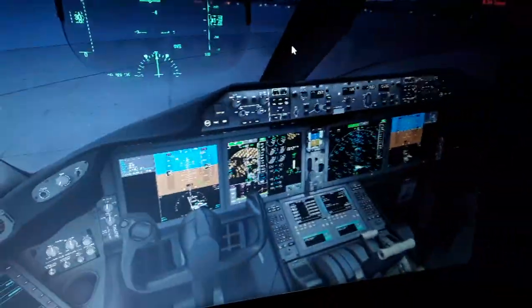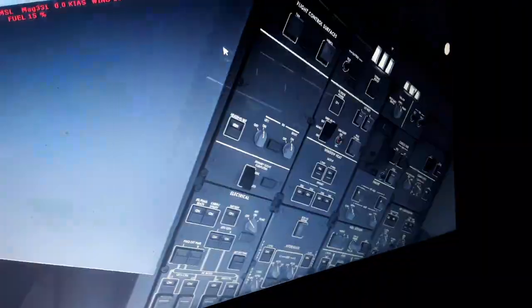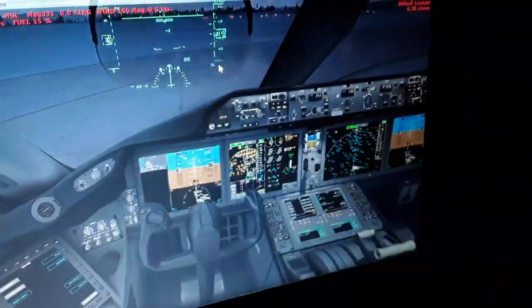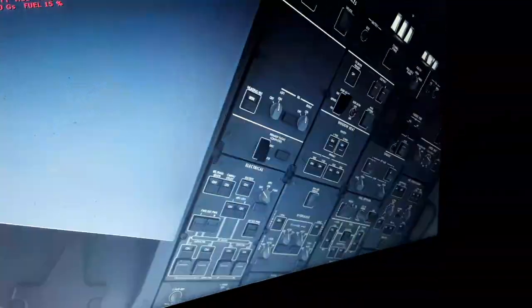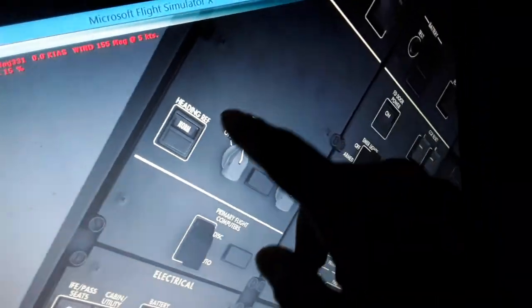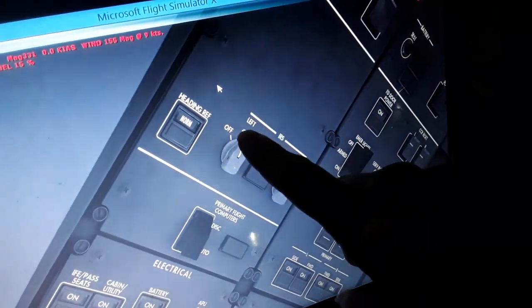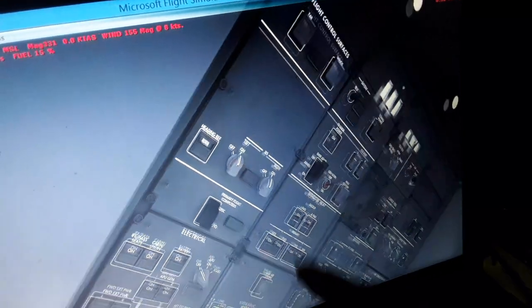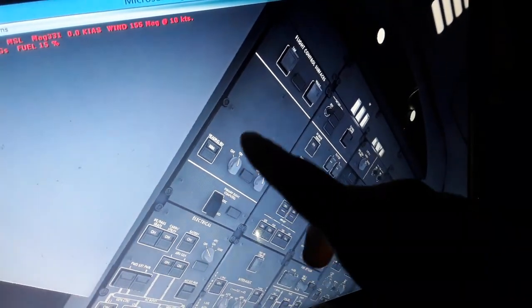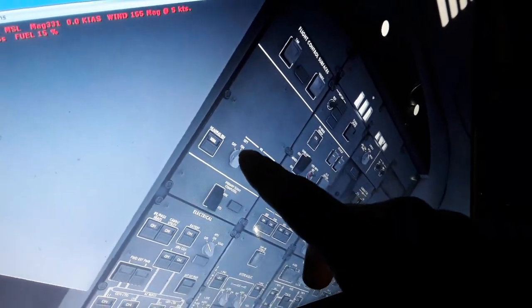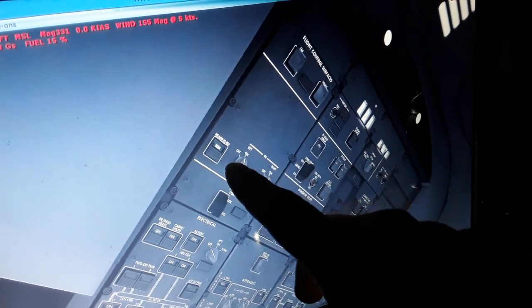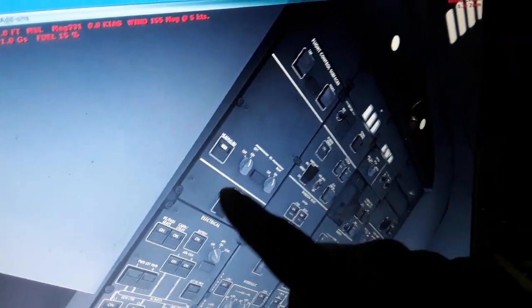So this is all the navigation air data. We have the air data computer in the overhead panel, so I will start turning to the overhead panel in a couple of seconds. This is the autopilot settings for the primary flight display. All the air data: airspeed, VC, altitude, barometric altitude, pitot static, pitot dynamic, the airspeed of the aircraft, laser gyroscopes for laser gyroscope alignment, inertial reference system, IRS alignment with the magnetic North Pole and the geographic North Pole, depending on where we are in the world.